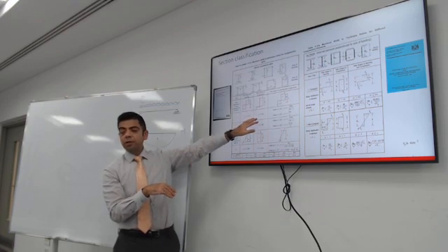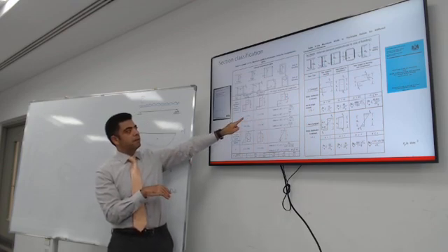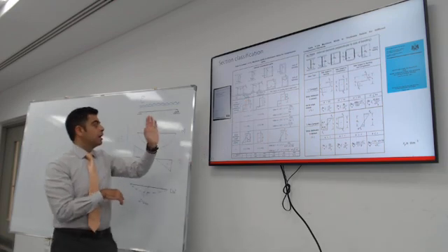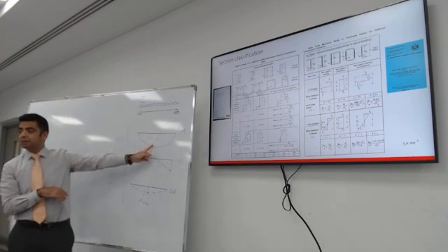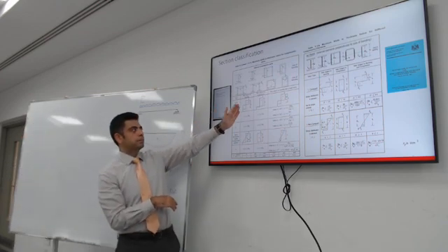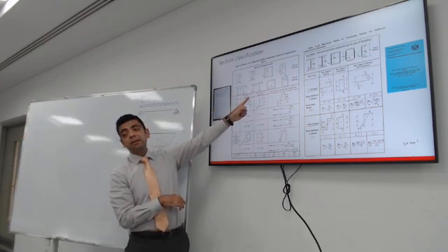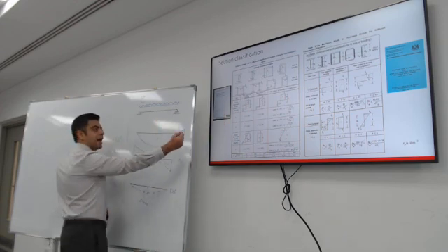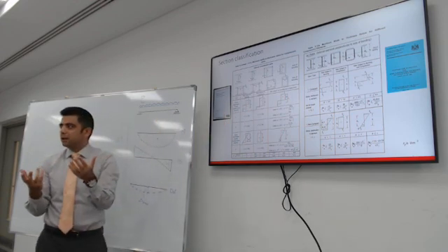How do you actually use these values? You just look at the definitions. If you're trying to design a beam for bending, you use the first column. It says part subjected to bending. If your beam has bending and axial load, you might be designing a column.